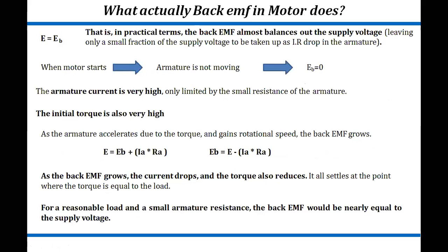So you will get an initial torque that is very high, because torque is nothing but the quantitative measure of the tendency of a force to cause relative motion. So we can take torque equal to F into R into sin theta. F is the force, R is the perpendicular distance, the radius of the object which is rotating, and theta is the angle between the force and the radius. So here you get the equation for the torque.